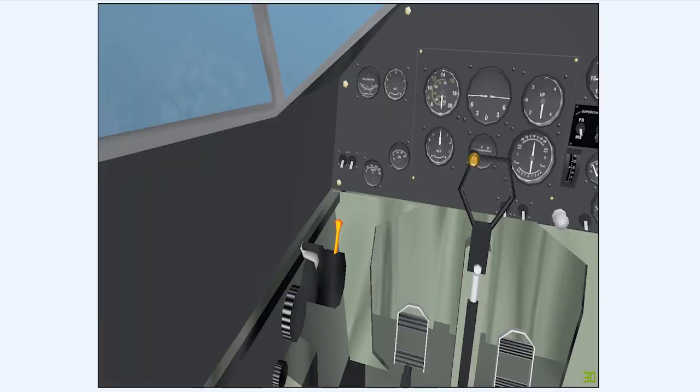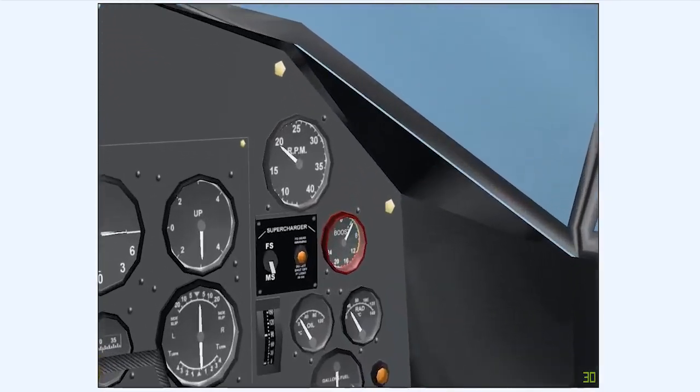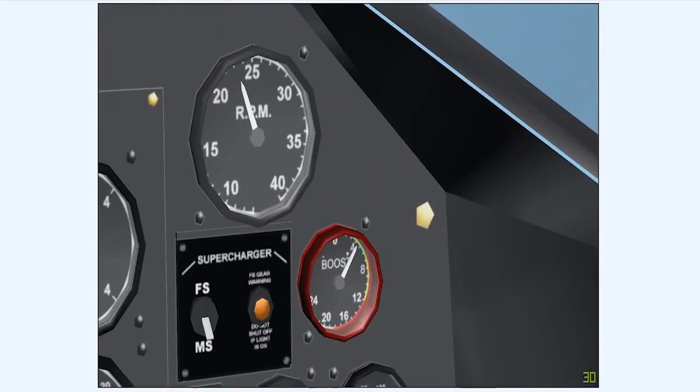Almost without exception, variable pitch propellers are installed on supercharged aircraft engines. A variable pitch propeller allows the propeller blade angles to be adjusted in flight between fine and coarse limits. This results in the RPM of the engine increasing or decreasing.